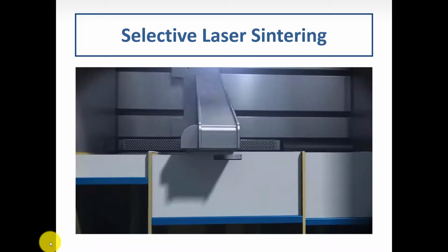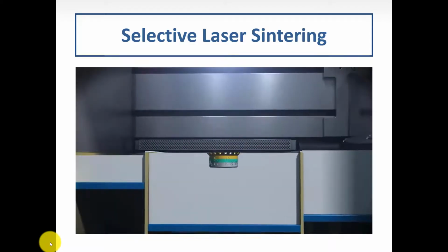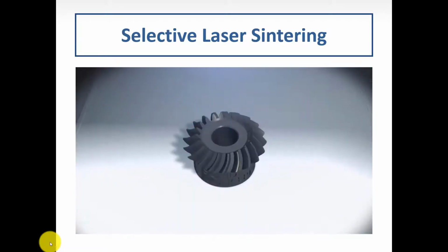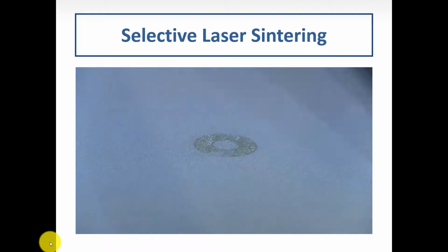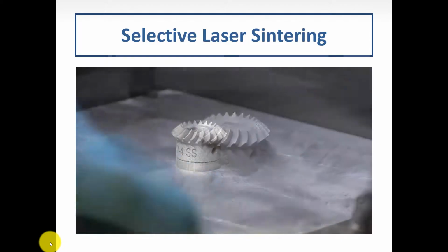Once a single layer is complete, the base plate is lowered just enough to make room for the next layer. More material is raised from the cartridge and recoated evenly upon the previously sintered layer. The DMLS machine continues to sinter layer upon layer, building from the bottom up. As the part is built, support structures are added to give supplemental strength to fine features and overhanging surfaces.